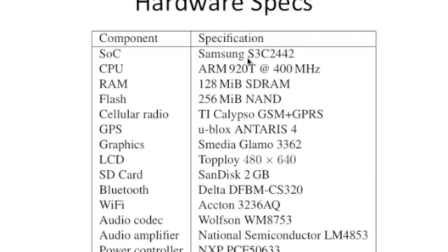So this particular system had this system on chip, that is this application processor, which has an ARM processor and certain other components like memories, flash, etc. So that makes it a system on chip. Multiple pieces are put on the same chip, and it was a system on chip from Samsung. The CPU was ARM, running at 400 megahertz, some memory, 128 megabytes, 256 megabyte NAND, modems, etc. Then they had a lithium-ion battery. So nothing exceptional about this system, just a typical smartphone system.